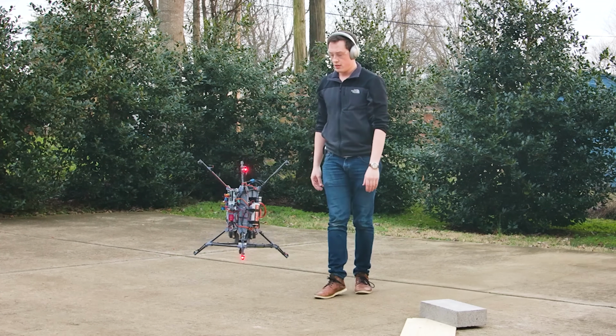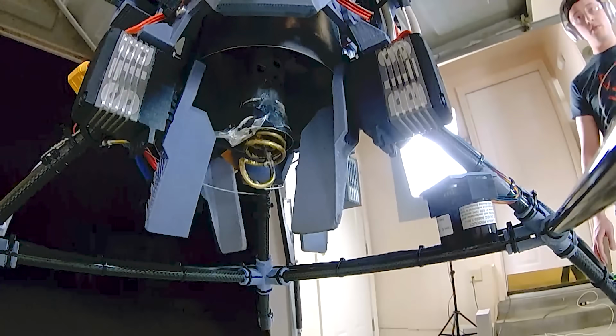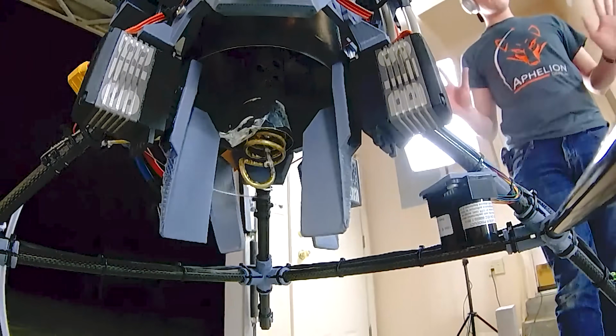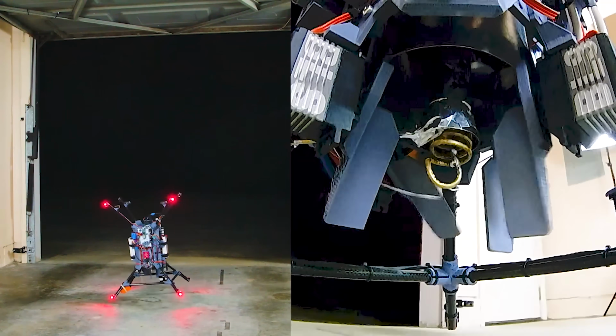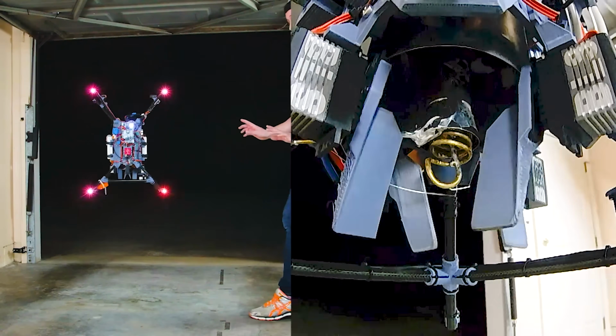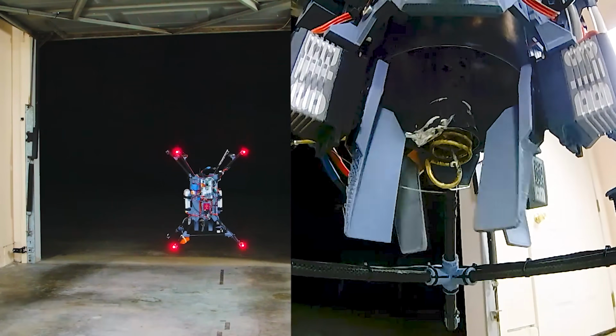What we had going on before was all of the roll torque being dealt with by the thrust vector control vanes. It worked, it was kind of okay. However, the problem was, and you can absolutely see the differences between different hops, especially earlier on, the hops look really, really rough. But we were getting really close to the stall point. Each one of these fins has a point at which it stalls and it can't provide any more torque. But when we canted the fin enough to resist those roll torques, when we canted that TVC vane enough, we were reaching the stall point. And it was letting the craft just spin out of control, basically.